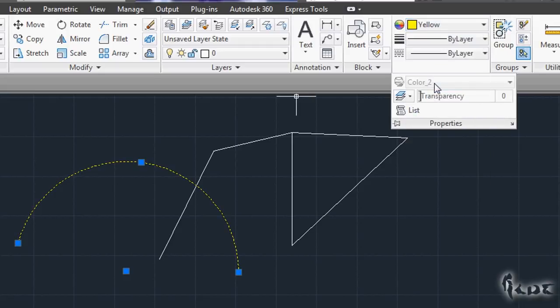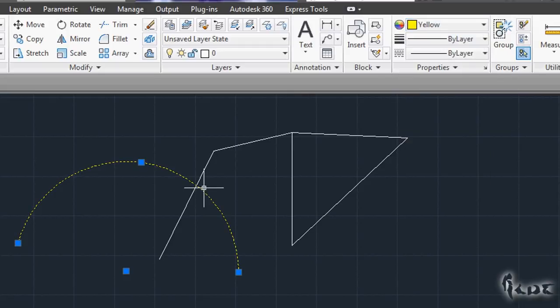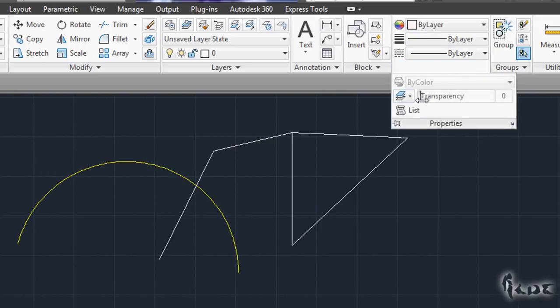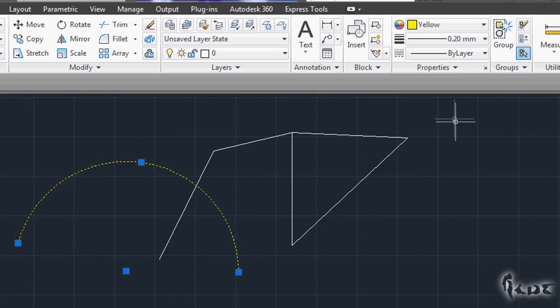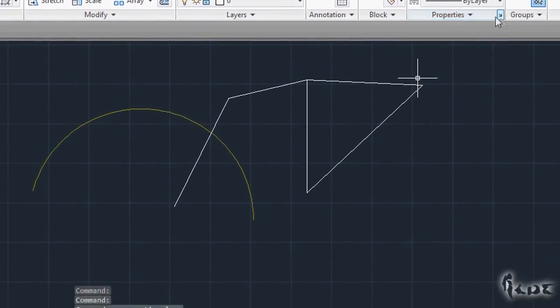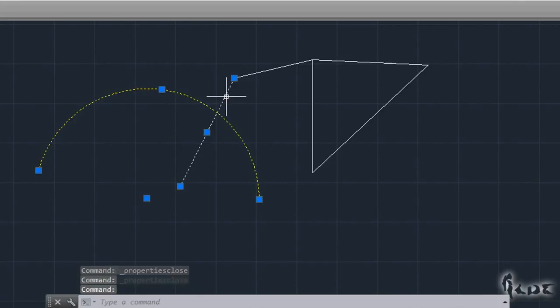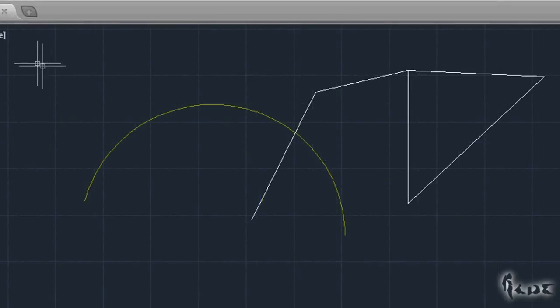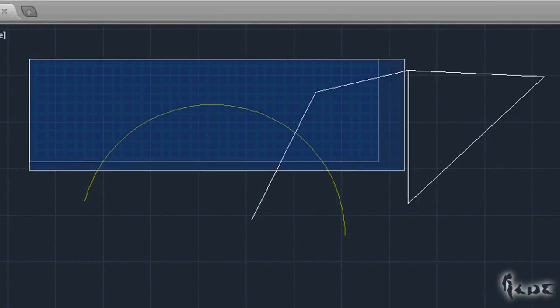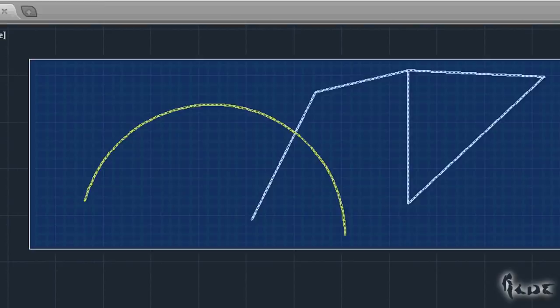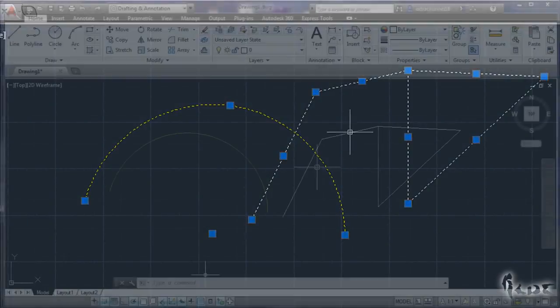For example, select an object and go to the Properties section. Here you can choose color, thickness, kind of line and transparency. Just click at the bottom. These are just related to the object currently selected. You will need to select more objects to apply the same properties all at once. To do this, you can select objects one by one by clicking on them singly, or you can simply click and drag your mouse across all the objects you need to select in one single shot.